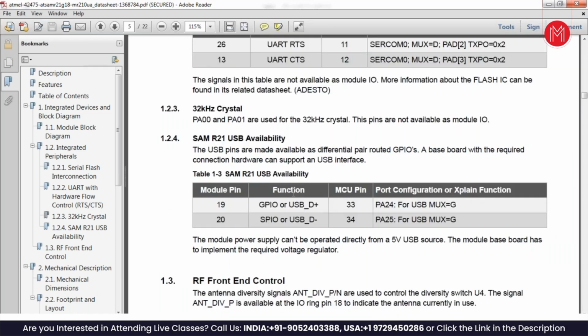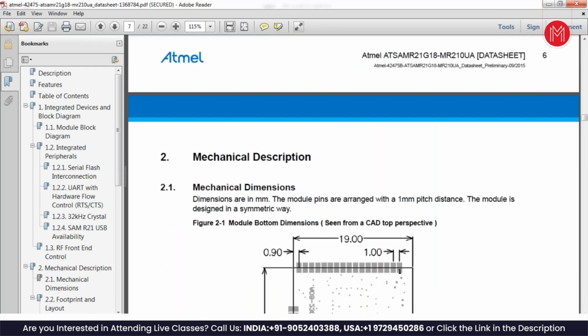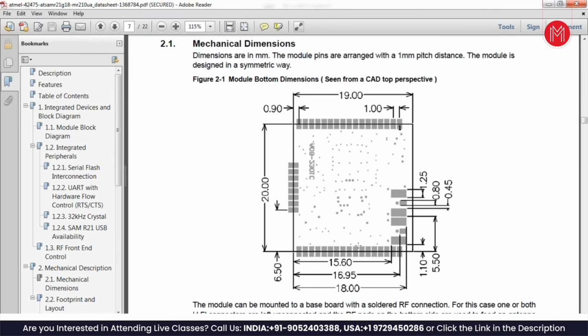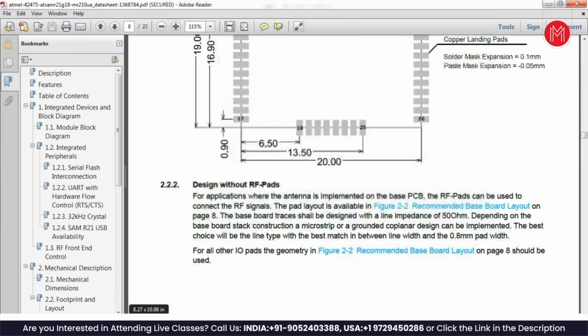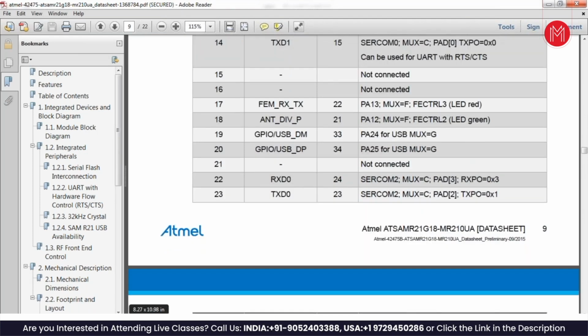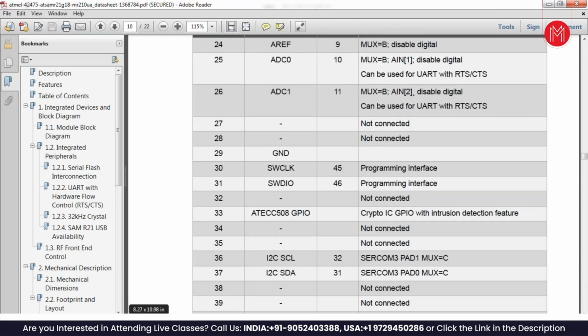So, main controller. Then it may have some signals that you transform. Those are all the pins that are there. SPI, we don't use. RXD, TXD are the ones on pins 22, 23, I think. It also has an I2C interface, but we need to see if it is available for the microcontroller.